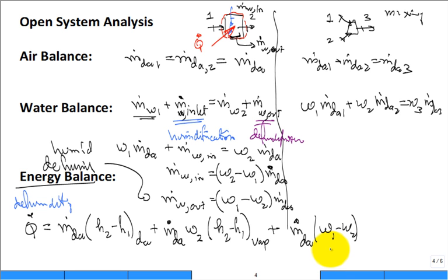That gives me how much is dehumidified, how much is the liquid flow rate. Isn't that the liquid flow rate? Times the exit enthalpy, H, maybe I should call it 3, H of the liquid going out. If you're dehumidifying, it's going to come out liquid, minus H of the vapor coming in at 1. Well, a very similar energy balance over here for the mixing.